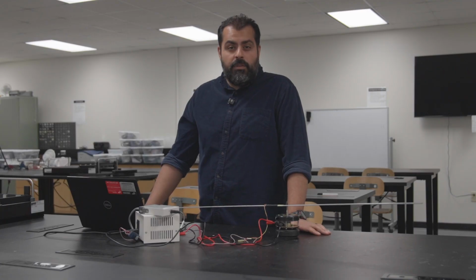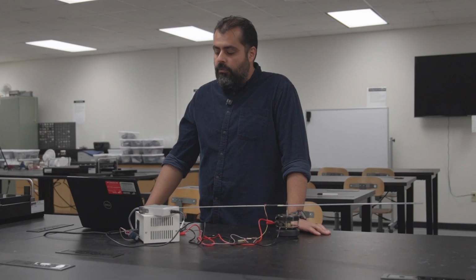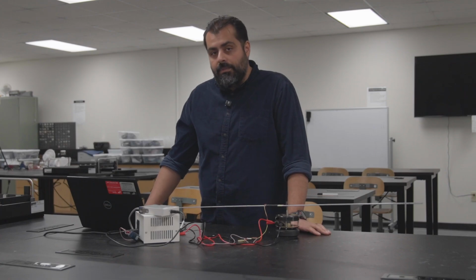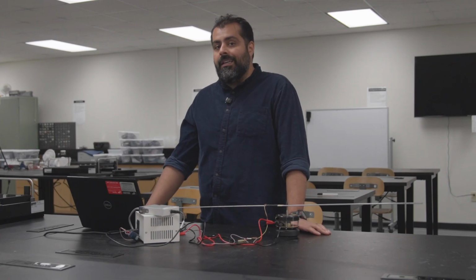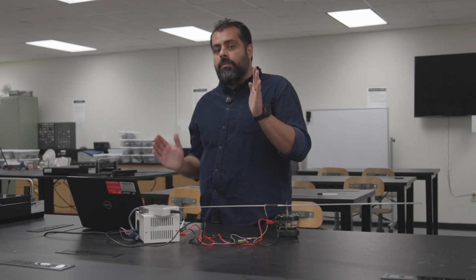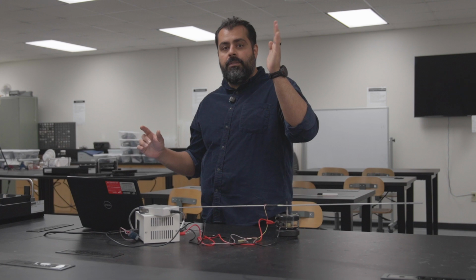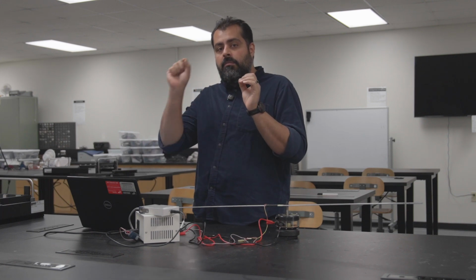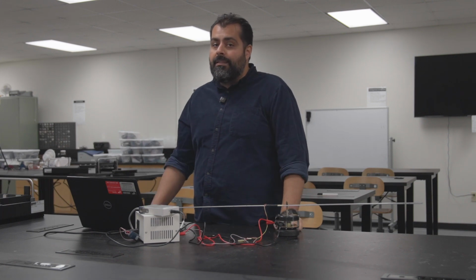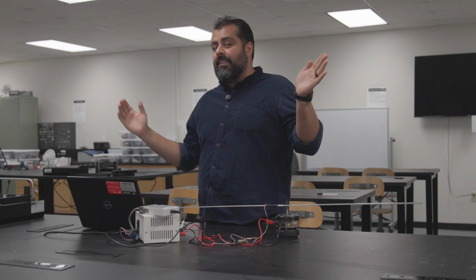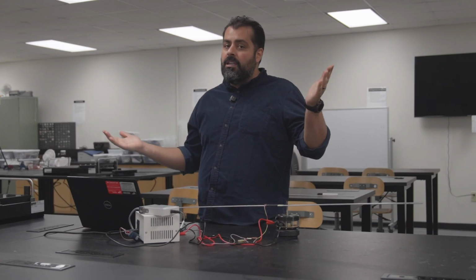And I guess the last point that I wanted to mention is for the last part of the structural dynamics lab, the damping ratio calculation. It doesn't matter which amplitude you choose, as long as you choose a higher amplitude and a lower amplitude, and you count the number of periods between them. So it doesn't have to be the first and the last one. Technically, there is no last one.